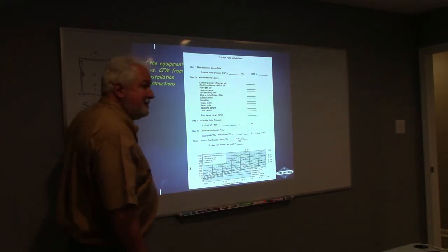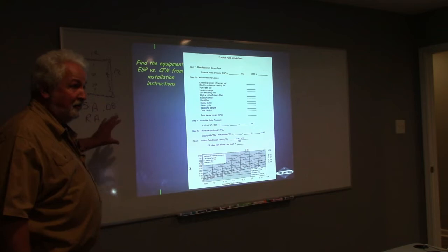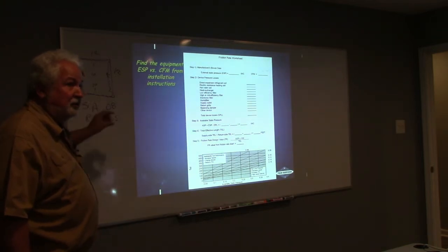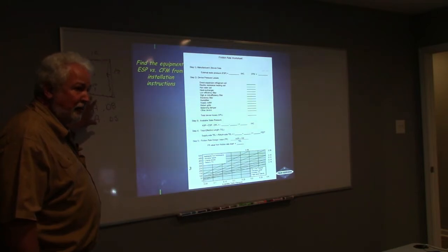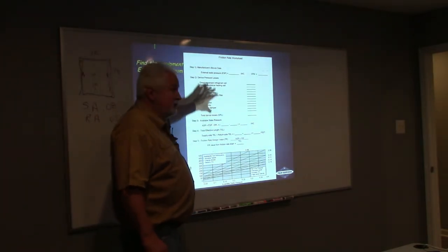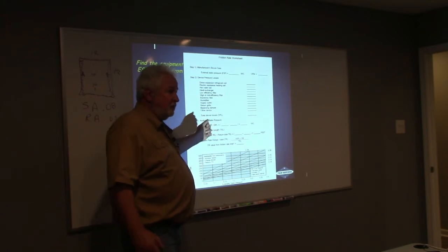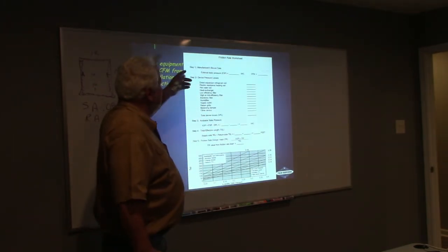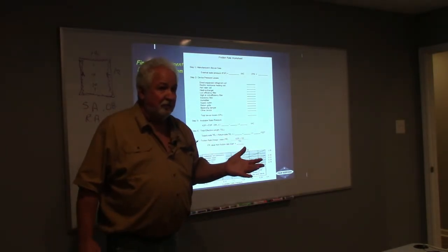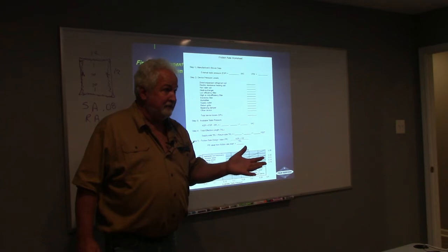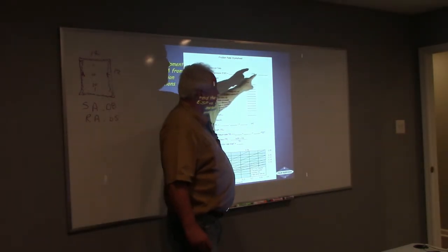I'm telling you, I think these numbers will be accurate 95% of the time for what you guys are dealing with here in this market. So I like to give you this as a good starting point. I'm going to make sure that he understands how to do this so that he can change it if he needs to. Fair? Cool. All right. So first of all, I've got to find out what the manufacturer said that blower can blow through. Yes? Good. So the first thing says external static pressure, inches of water column, equals CFM.